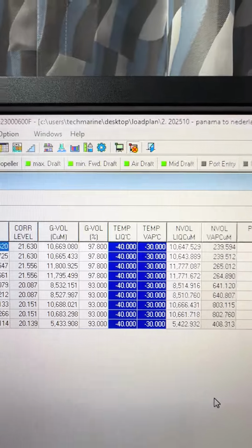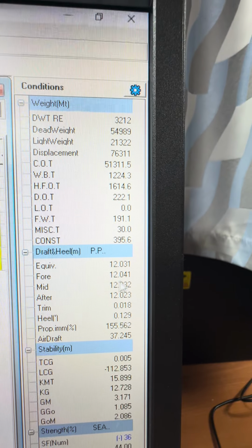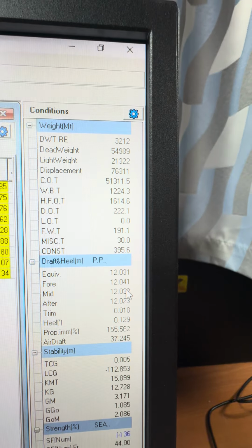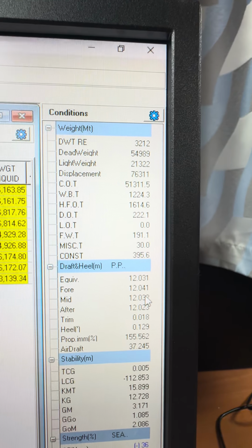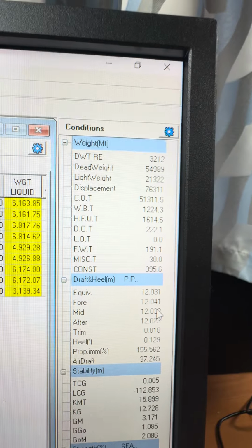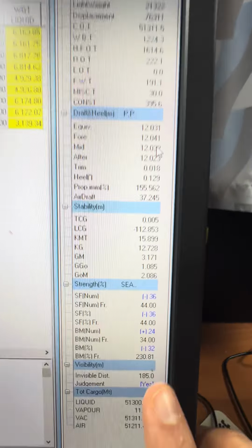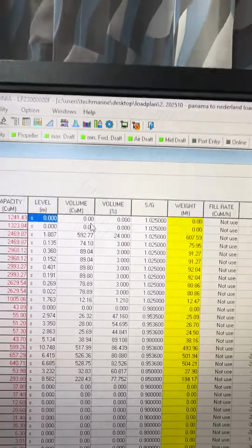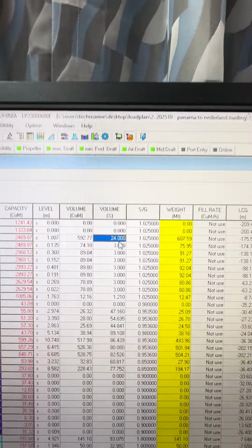The reference point is loading temperature. That's why this was our last loading. Here you can see our draft is 12.14, it's draft in fresh water. Because we have a restriction at Netherlands, it must be less than 12.19. It's restricted by our summer draft as well, and it was a restriction by the port. And here the trim. Finally you can see that we don't have list, it's almost 0.1, and all ballast tanks are almost empty. Only 24% at one port for list correction.